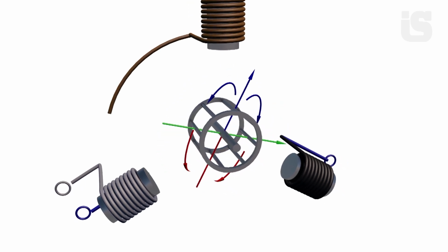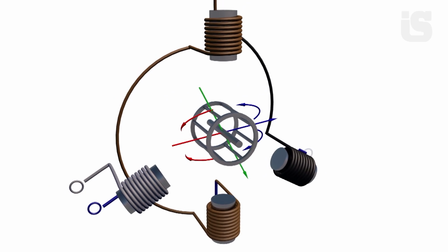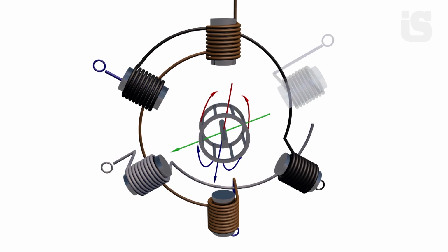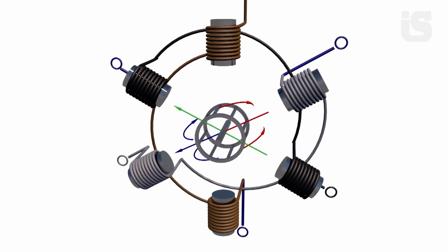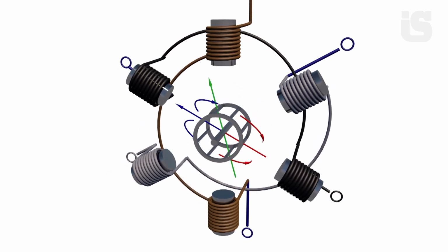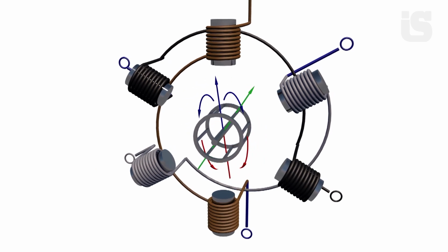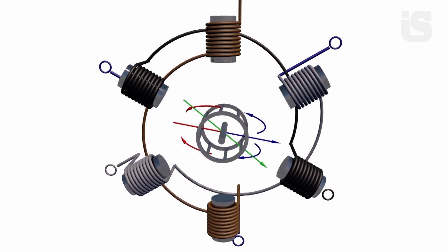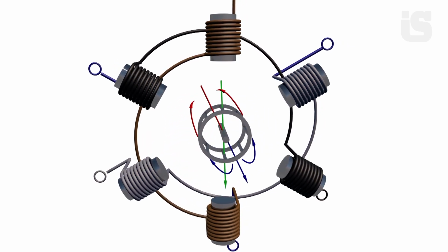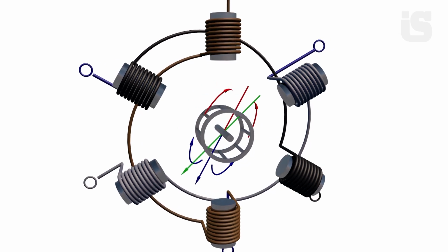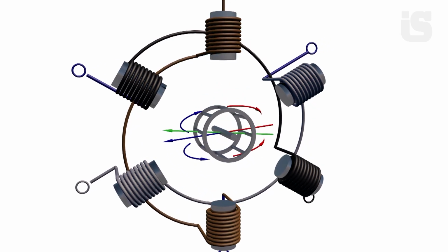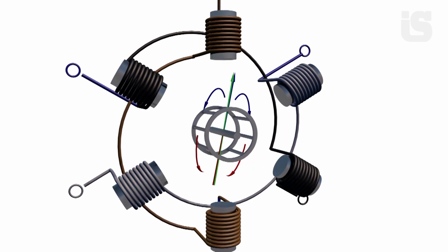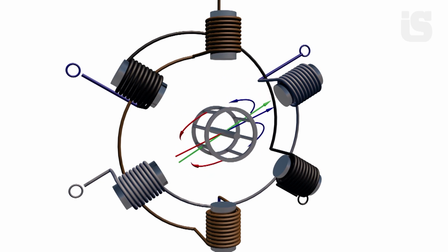Stator electromagnets are often arranged in pairs or symmetrically. This arrangement is necessary to create a uniform rotating magnetic field, in which one set of coils acts as the north pole and the diametrically opposite set acts as the south pole, ensuring effective interaction with the rotor. Key feature of a paired configuration: symmetry. The coils are arranged on the stator core with equal spacing to ensure a balanced magnetic flux. The pairs of coils are connected in series to create opposite poles.